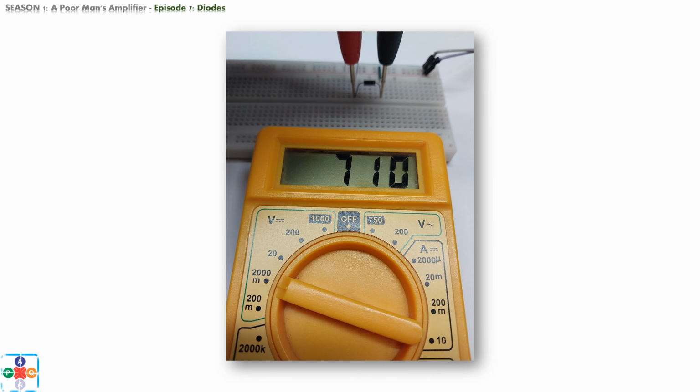As you can see, we get a value of 710 millivolts, which rounds up to the predicted 0.7 volts for a general-purpose silicon diode. The discrepancy between multimeter testing and test circuit readout is due to the difference between the two DC sources, and the value for current flowing through the circuit. The UI characteristic of the diode is not linear, so this discrepancy is to be expected.